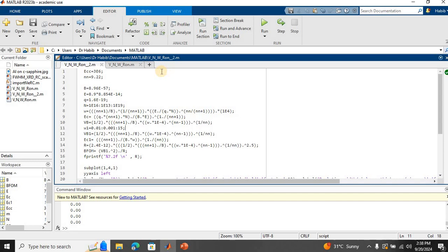So here are some basic parameters for gallium nitride. For example, Ec over here represents the critical electric field of gallium nitride in volts per centimeter. It's 3×10^6 volt per centimeter. Gallium nitride has a very high breakdown electric field, making it ideal for high power applications.